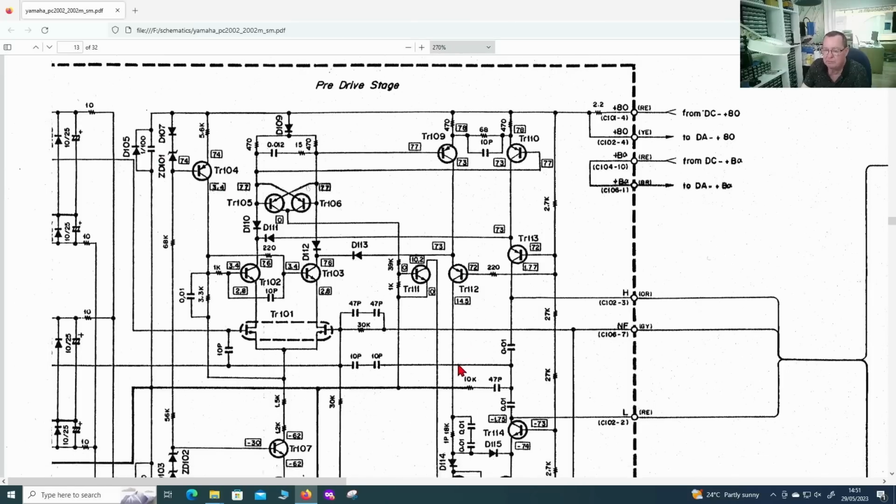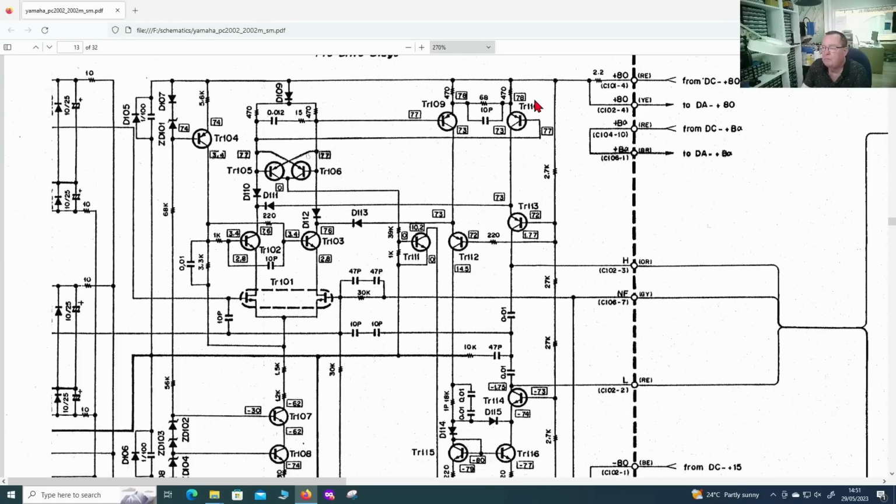What else would cause it? Well, as I say, all these paths I can see all go through a higher value resistor. If we had a short circuit diode, the next thing we've got is 470 ohm resistor, so it can't be down that route. Can you see what I'm doing? I'm trying to find obvious routes where the low resistance is. I can see that.